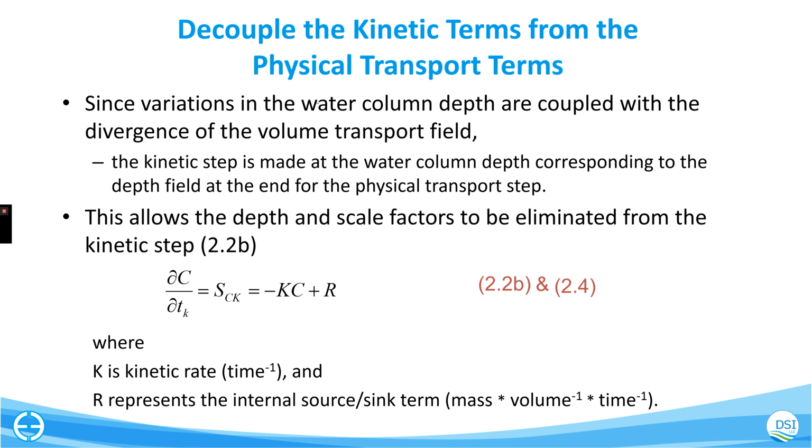I'll just mention it here. You specify all your kinetic rates in the equation. However, water quality kinetics do not operate at the same time scale as your hydrodynamics. Your hydrodynamics are typically solved on the order of a few seconds or less.